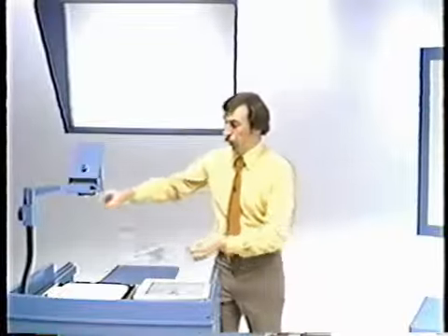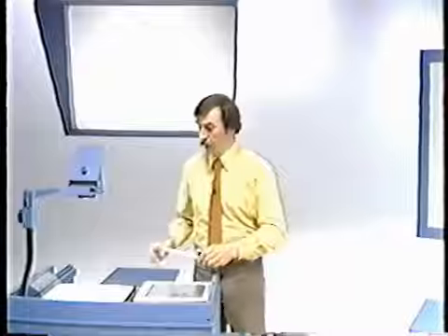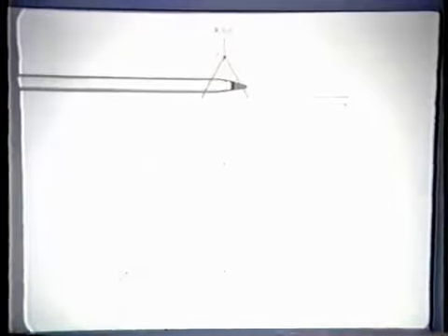Well, let's choose some type of simple representative spectrum. And of course, what's important about it is that the spectrum that we choose is band limited, or that there's an anti-aliasing filter. And it's not the shape, of course, that is critical. And as we work our way through the system, this is the continuous time spectrum. After sampling, that spectrum is replicated at integer multiples of the sampling frequency.